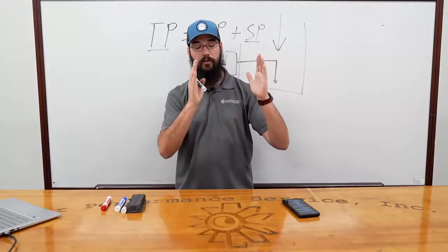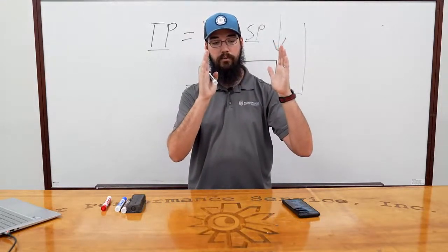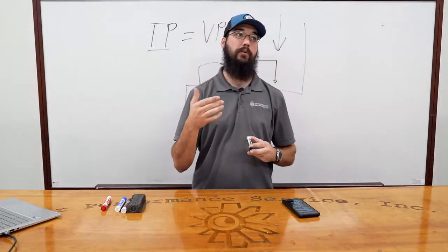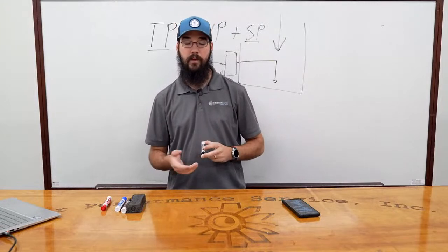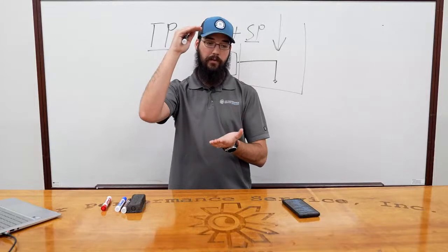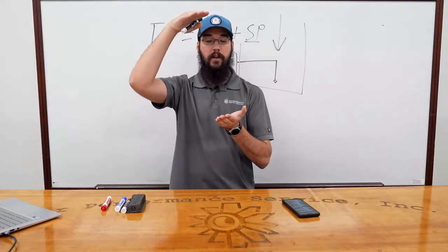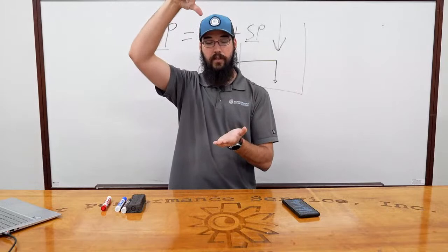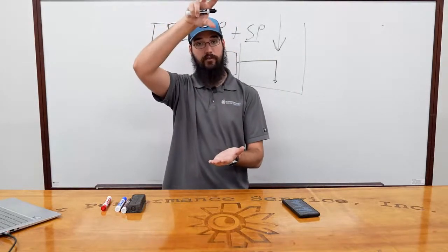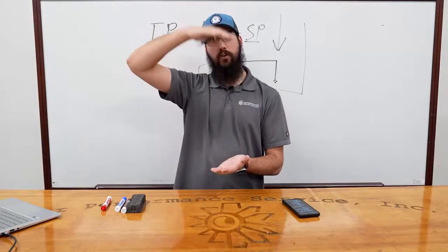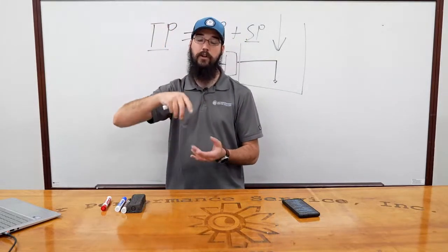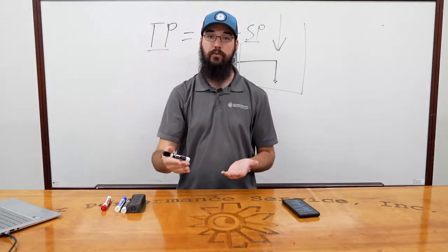There are some units you'll have a pressure drop chart for just the coil. For example, when you're doing a furnace system, a lot of times, the coil itself is a separate component from the actual furnace, and so you can actually just change out just the coil. At that point, you would have a coil pressure drop, and that could help you calculate via the chart what your flow is through that coil.